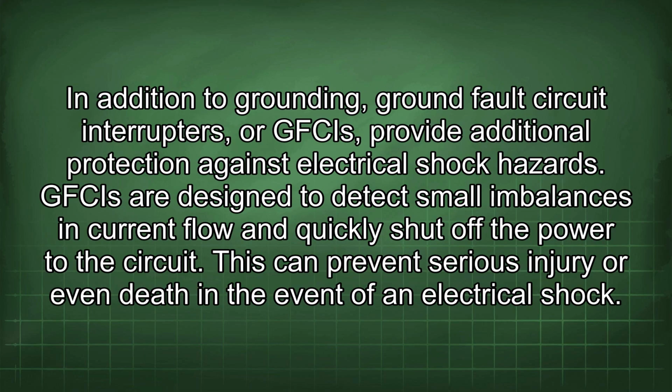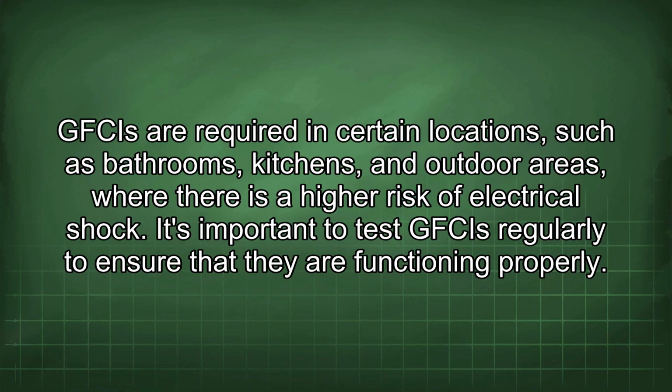In addition to grounding, ground fault circuit interrupters, or GFCIs, provide additional protection against electrical shock hazards. GFCIs are designed to detect small imbalances in current flow and quickly shut off the power to the circuit. This can prevent serious injury or even death in the event of an electrical shock. GFCIs are required in certain locations, such as bathrooms, kitchens, and outdoor areas, where there is a higher risk of electrical shock. It's important to test GFCIs regularly to ensure that they are functioning properly.